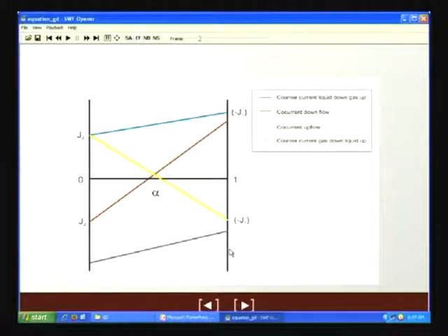So, therefore, co-current downflow and co-current upflow intersect the x axis. That means for co-current upflow and co-current downflow, naturally both of them have the same sign, or in other words J2 is positive, J1 is positive, or J2 is negative, J1 is negative, as a result of which we get J2 positive, minus J1 negative for co-current upflow, and J2 negative, minus J1 positive for co-current downflow. Agreed? So, therefore, what do we find?